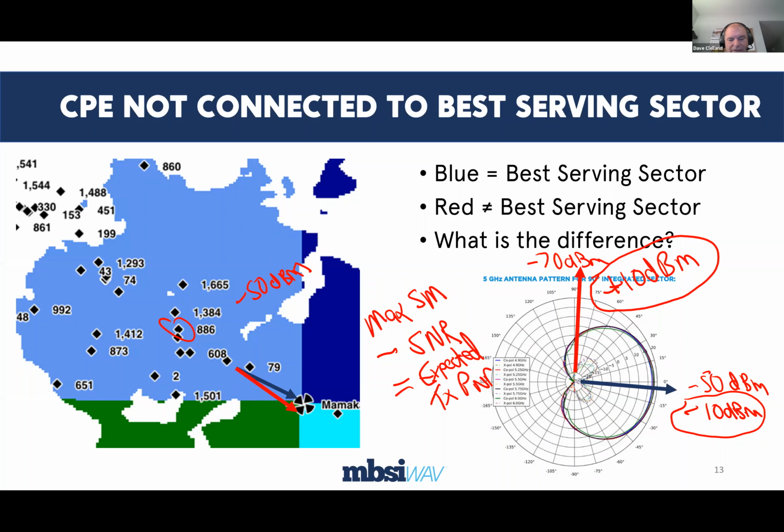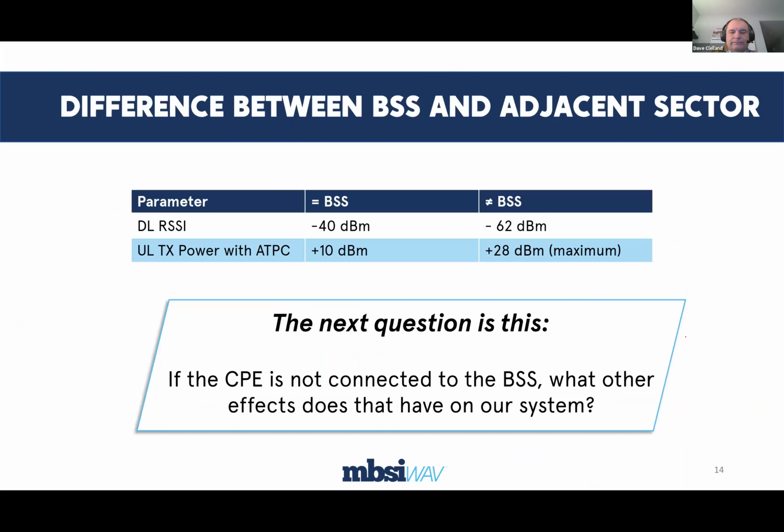It's going to be received, of course, on the red, which it's connected to, and it's generating a transmit power signal. The red connection here, the southwest sector, is telling the CPE, the SM, to transmit at a very specific level, in order to look like all of the CPE that are in the green sector here, because in fact that's what we're saying, that this is a green sector, but it's in the middle of the blue. So we have some problems that result.